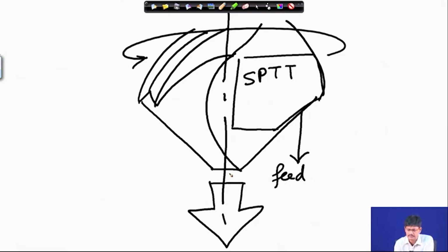How can a single point turning tool simulate it? Yes, there is a similar tool which can be supposed to be on the other side doing the very same thing. So, a drill may be considered to be a case of two single point turning tools attached together. Now, let us see the other view of the drill.